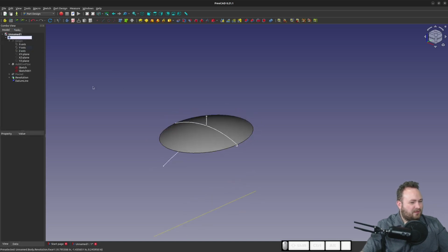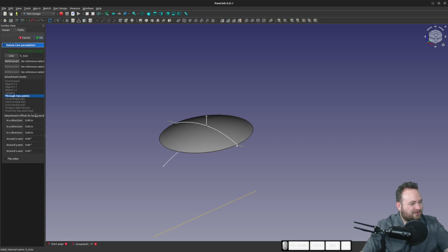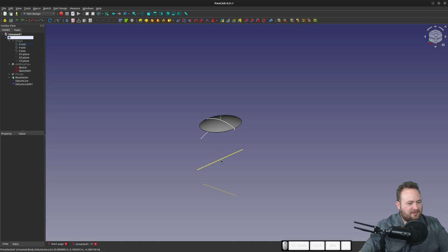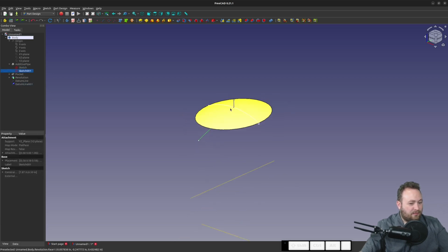Next, I want to stand on my x-axis. Grab my line. And on my x-axis, I guess it's still going to be in the y direction. We're going to say negative 200 millimeters. Just like that. Perfect. So this marks the center of this arc, and this marks the center axis of this arc. And we want to have those references because now I'm going to do a multi-pattern.